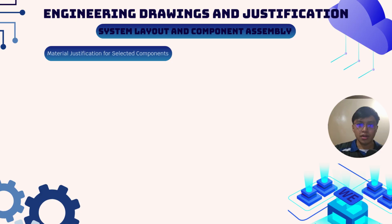For the spur gear train, we upgraded to AISI 4340 normalized steel. This deep hardening alloy is incredibly tough, allowing the gears to handle high torque and contact stresses without pitting or bending over thousands of cycles. To keep the system running smoothly, the UCP 208 bearing housings are made of gray cast iron. Its unique graphite flake structure acts as a natural dampener, absorbing vibrations from the motor and belt to ensure quiet operation. To secure these components, we are using ISO class 8.8 steel fasteners.